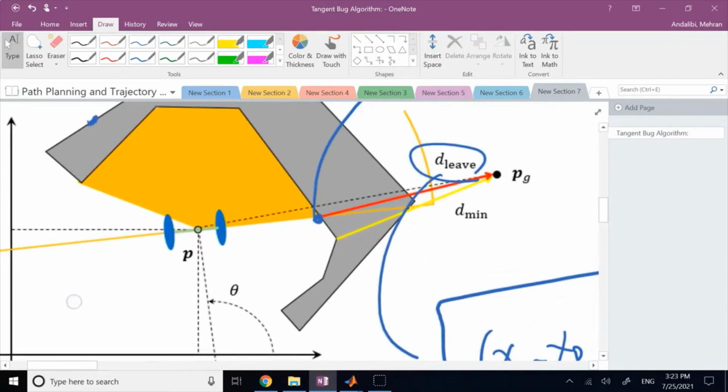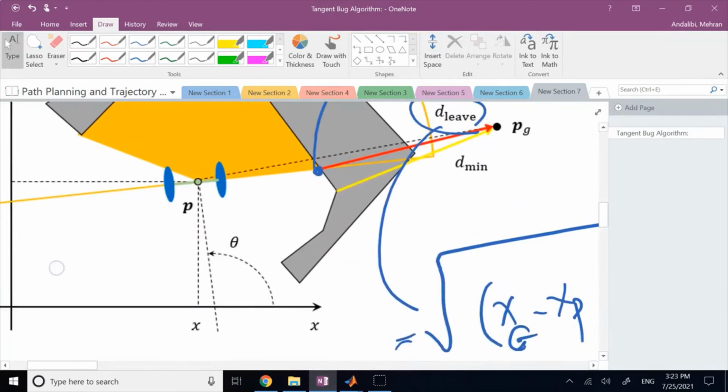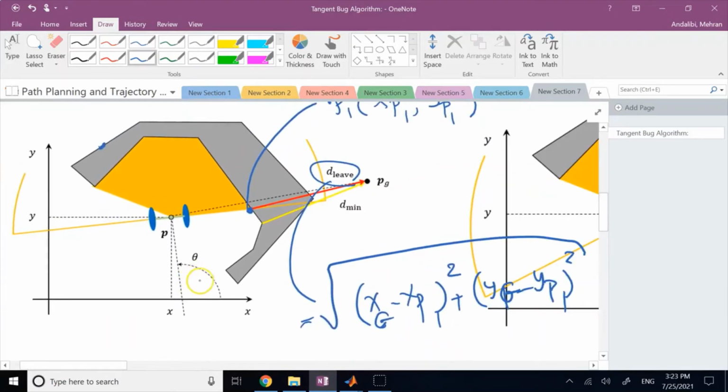So what you need is, if you have your current location and the relative angle between the center of the robot and the point, you know that point comes from this angle here and this distance d. d is the distance between P and that endpoint. So that's what your scanner gives you. Your scanner gives you a bunch of angles and a bunch of distances, right?